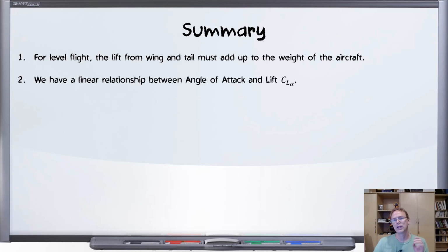After that, we reviewed that lift curve that we got from the wind tunnel data, and we showed that it was a straight line, at least in the region that we're going to be working. We gave the slope of that straight line the name CL alpha. And that stands for how does the lift coefficient, CL, vary with alpha.